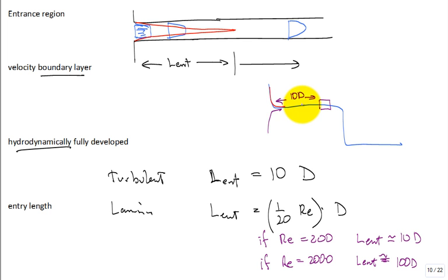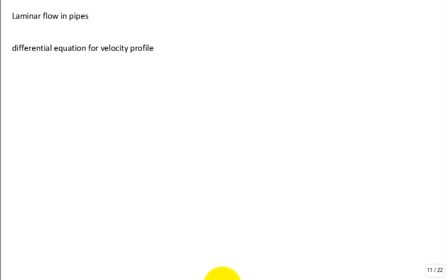And if you ever go out and practice and you're working as an engineer, you have to walk through facilities and look at flow meters, or put in the flow meters, or check the flow meters. It's not uncommon to find that whoever installed it found that there was some obstruction or something that prevented them, and they snuck it in at 2 diameters or 3 diameters afterward. What's it going to do? It's going to give you a bias in that flow meter. It'll be a continual bias in the reading of that flow meter. So that's one thing to have fully developed flow.